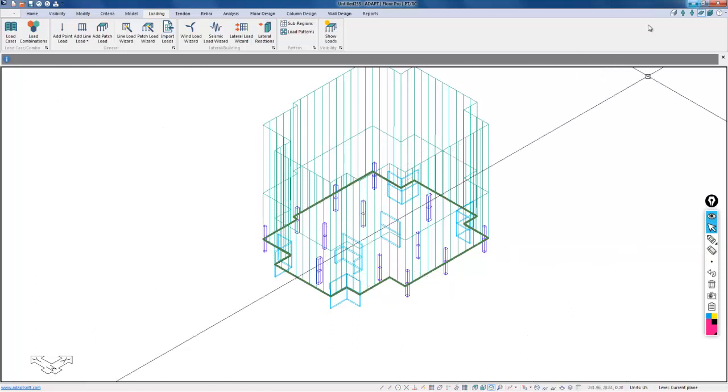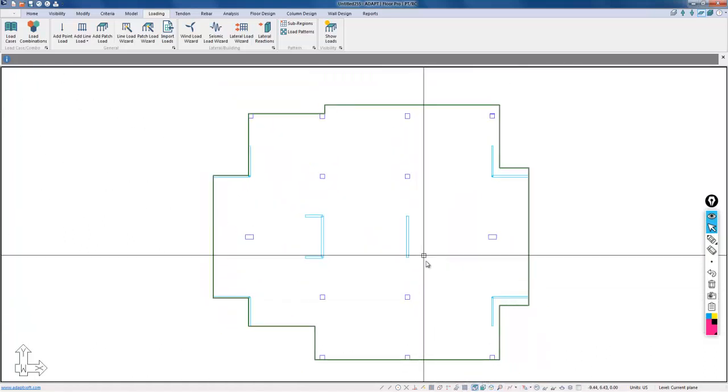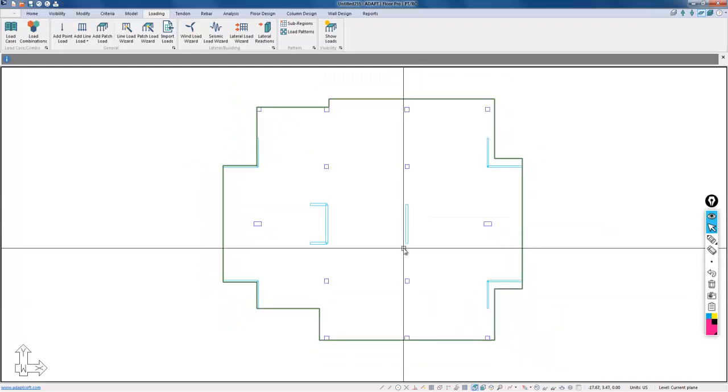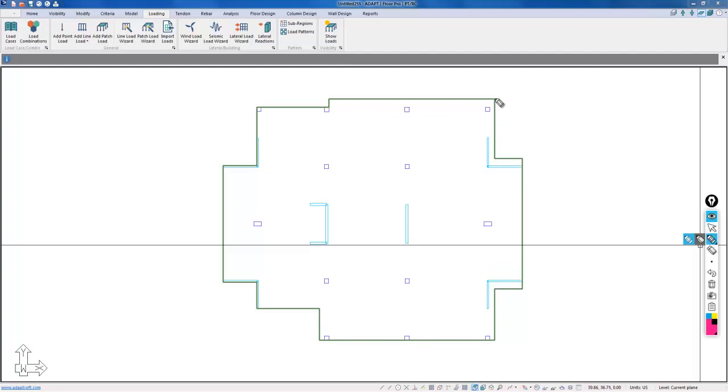So let's go now to the top view. We have our base loading. We're going to again assume that this is a loading that the slab was designed for. It's the total service load, for example, from the original design. And now we're going to add this new tenant load. So we're going to assume that in this region here there is an additional new live load of 100 PSF. Actually, we'll use something a little smaller. That might be excessive. So we'll say 75 PSF.